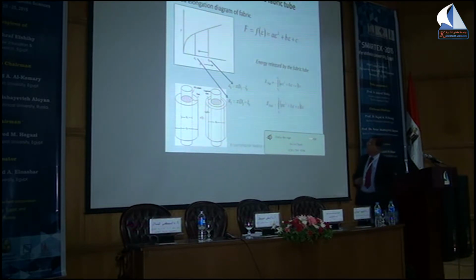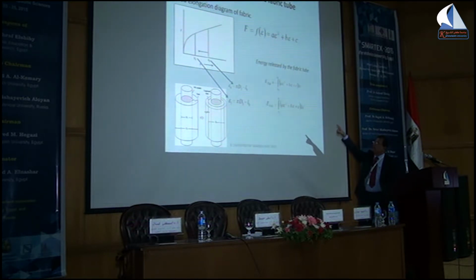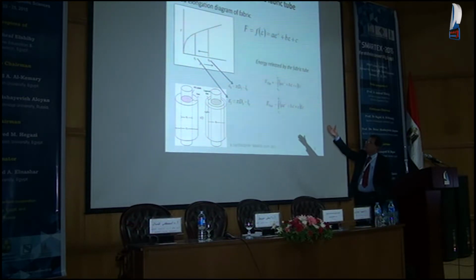So the fabric load elongation graph can be characterized by these quadratic equations, and the energy released by the fabric, which initially is traced from a value epsilon 0 to epsilon 1, we can find by integrating this equation.